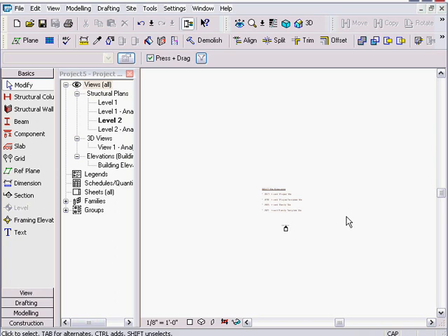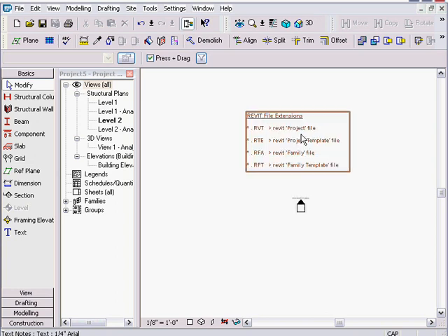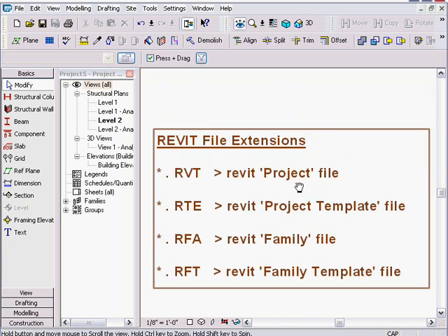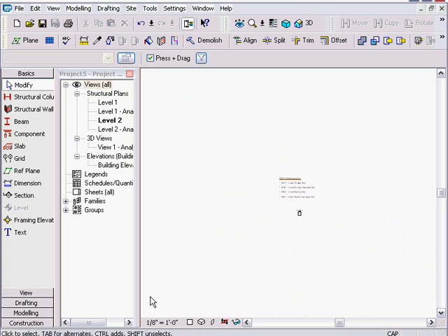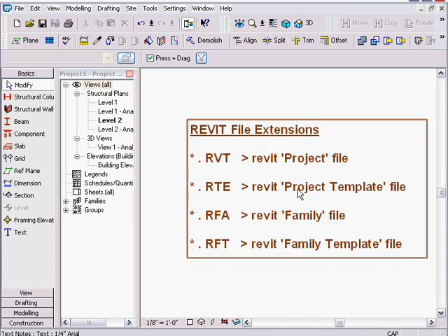And I've just got some text in here, and I notice as I'm zooming around one thing, if I'm going to zoom in on some notes here that I've made. Just as an added note, I notice that some people don't realize if my mouse is over here and I wheel in to zoom, it'll go that way. If my mouse is down here and I zoom in, it'll go this way. If my mouse is over here and I zoom in, it'll go that way. If my mouse is right over top of where I want and I zoom in, it zooms in on that area. So a lot of people don't realize. I'll see them zooming over here and they never seem to get what they want. Hover over the center of what you want and then wheel in with your wheel button and your mouse.